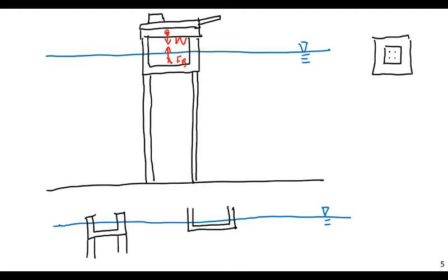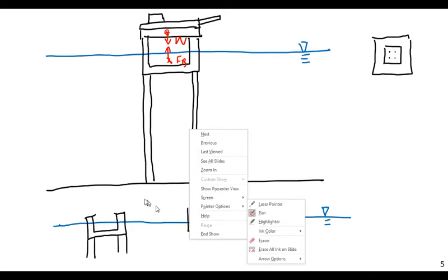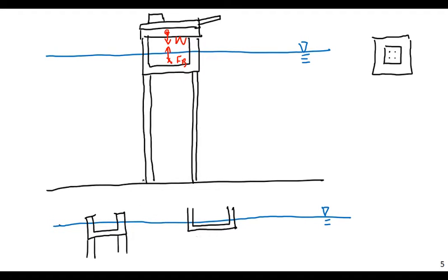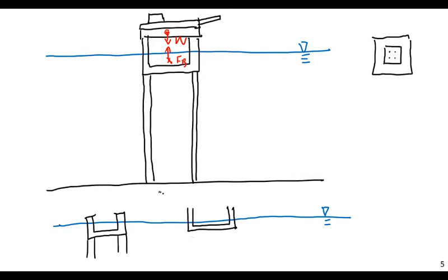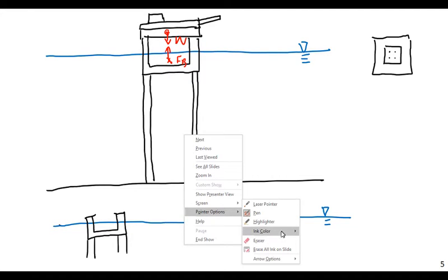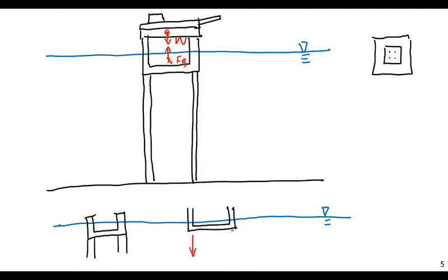It's now floating higher in the water, and because the tendons are anchored to the seafloor, this generates an immense tensile force in the cables, in the tendons, simply via flotation. So you float this thing out there, with it low in the water line, because the tanks are mostly full, you attach the tendons to them, then you pump the water out, and now the cables go extremely taut, and they are going to generate an immense tensile force at the legs of the hull, or of the structure here.